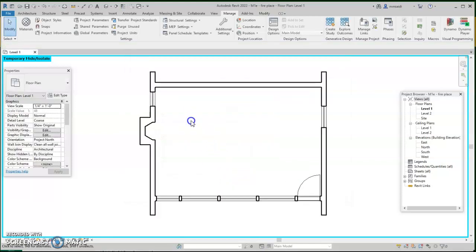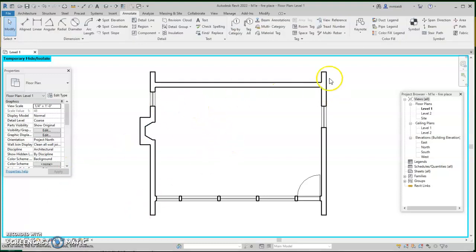Look at it. It looks thicker, and it looks a little bit easier to distinguish what I'm cutting through and what I'm seeing in the background. Now we're going to learn how to color and create regions. We're going to color the section cut lines, the walls. In essence, we're going to create regions.